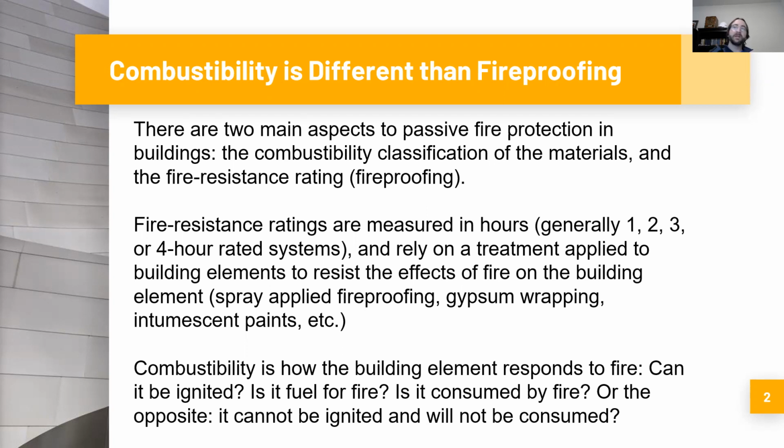But combustibility, on the other hand, this is different. Combustibility is how the building element itself responds to the fire, meaning, can the building element be ignited? Is it fuel for a fire? Can it be consumed by the fire? Think wood, of course. Wood-based building materials are combustible. They can be ignited. They can burn. They are consumed by a fire.